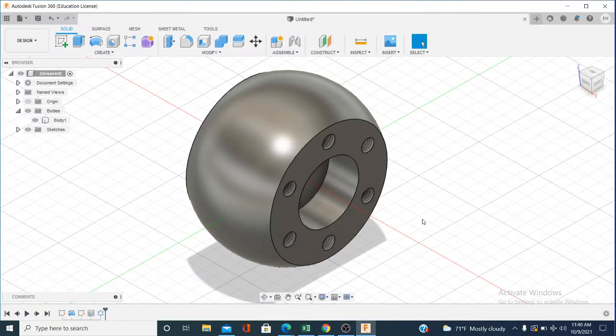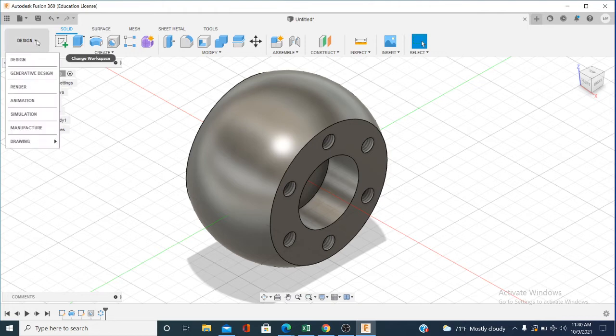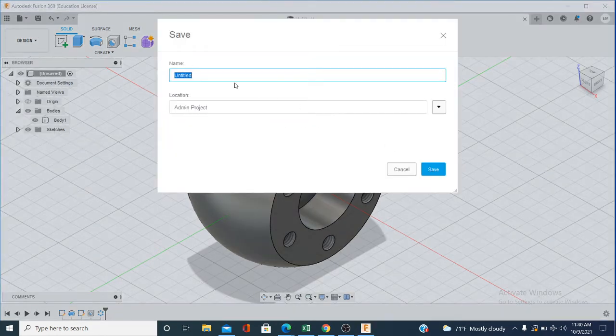All right, so now we're going to make a drawing of this. You come over here and click down on this icon and come to drawing from design. And the name of this drawing, we'll just go ahead and call it Revolutions-2 because I already have 1. You can call it a 1 if you want to. So Revolutions-1 Fusion 360, you should call yours.